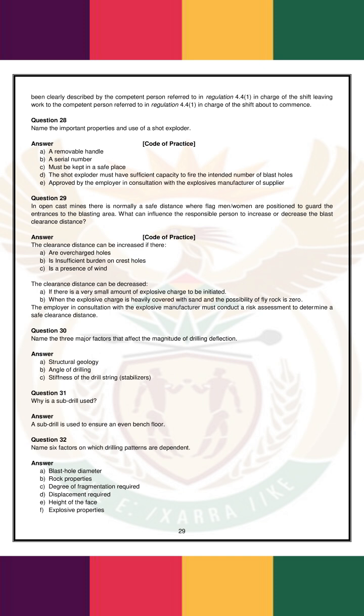The clearance distance can be decreased A. If there is a very small amount of explosive charge to be initiated. B. When the explosive charge is heavily covered with sand and the possibility of fly rock is 0. The employer, in consultation with the explosive manufacturer, must conduct a risk assessment to determine a safe clearance distance.